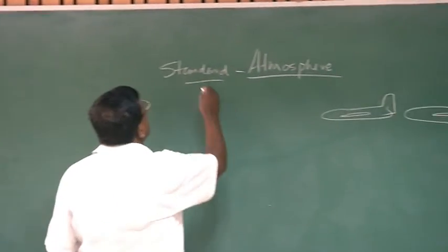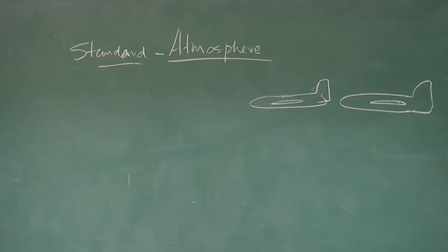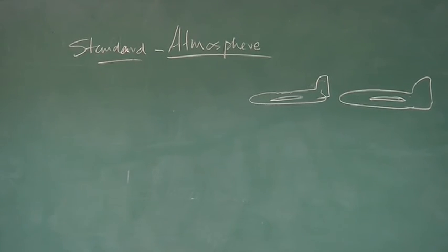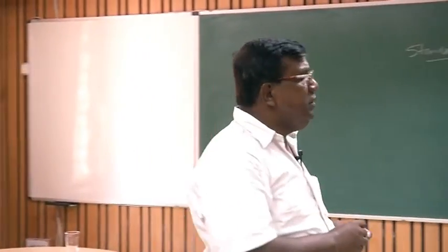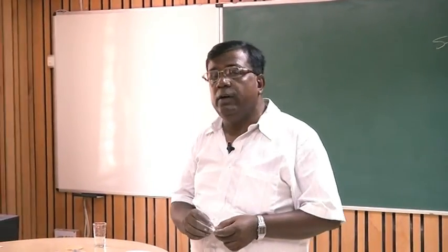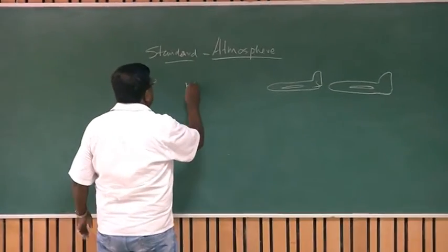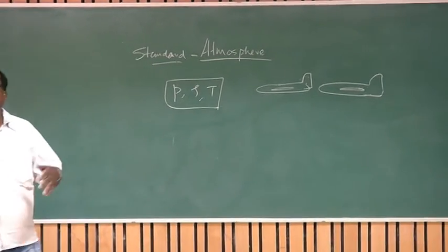That is where this concept of standard atmosphere came into the picture. We will develop an already established methodology based on experimental results, with the assumption that air behaves like a perfect gas. That is, we will assume P equals rho RT is valid, and we will describe pressure, density and temperature as we go higher and higher.